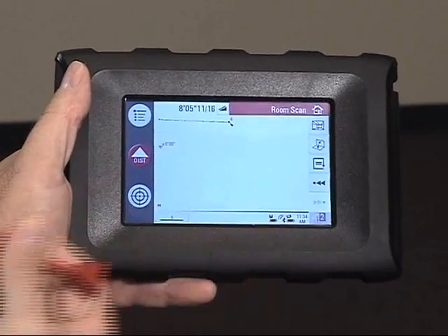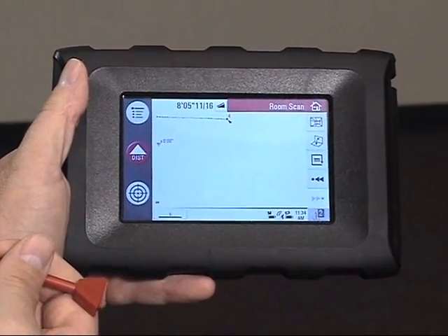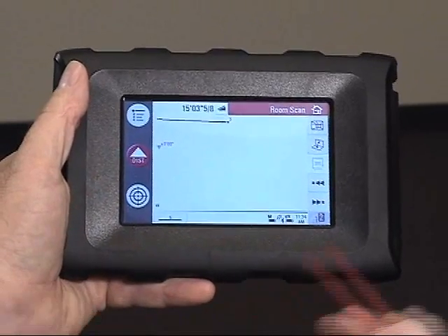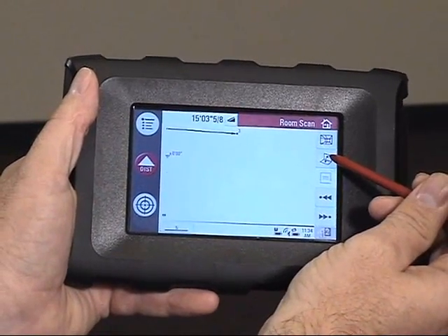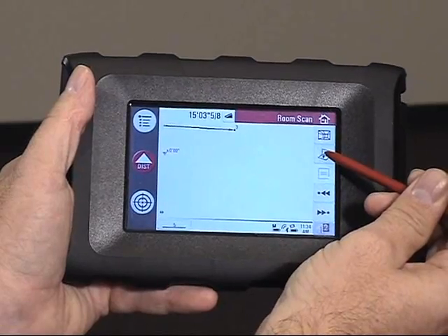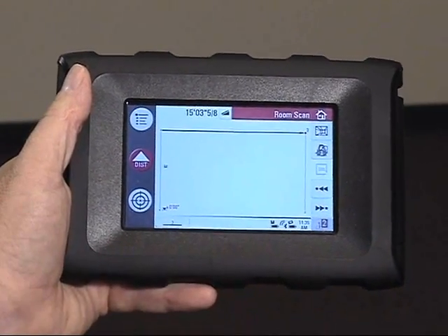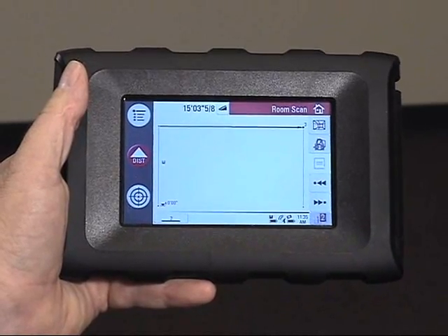themselves. In order to see this view now in a front-on view, we're going to have this line selected, which is a horizontal line, and the second button down on the right-hand side is the unfold button. So we're going to go ahead and tap unfold. You will now see in my view screen that I've got a front-on view of that wall plane.